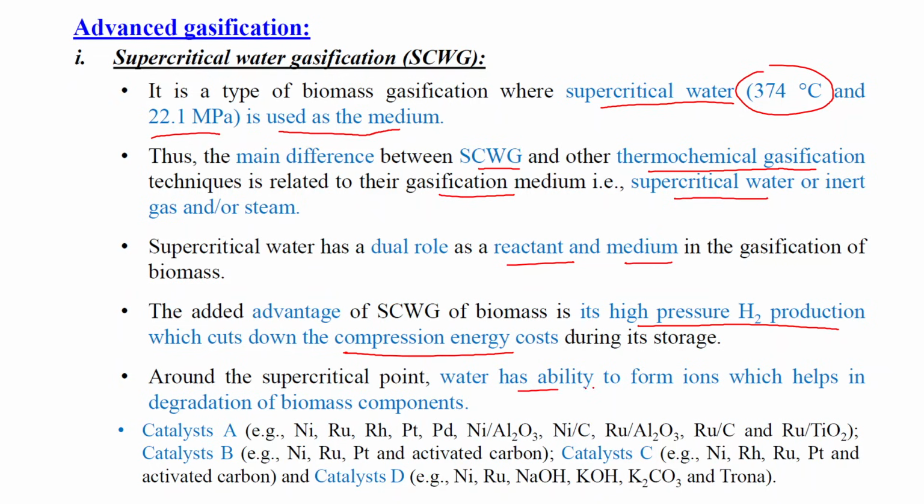Another advantage is that at the supercritical point, water has the ability to form ions, which helps in the degradation of biomass components. If different biomass components are present, side products will be formed, some undesired hydrocarbons. Those undesired side products are degraded in the presence of these ions, which assist in the degradation of biomass components. So that is also an advantage.